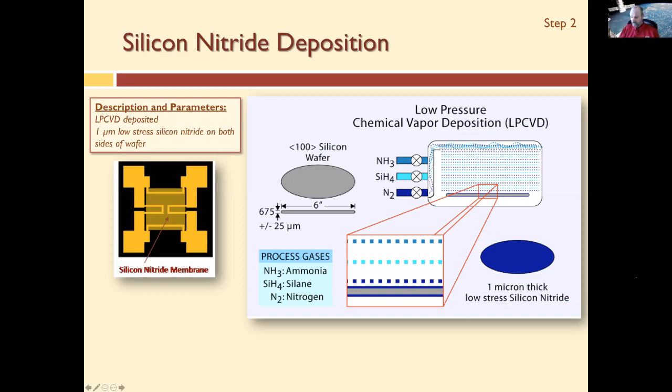Joshua asked, is most polishing universal across the wafer? Or are there specific polishes for certain applications? Yeah, you can get highly polished wafers that are super flat. So we usually have a flatness specification, right? They'll specify how flat it is overall over the whole surface of the wafer, and then how flat it is across a small section of the wafer.